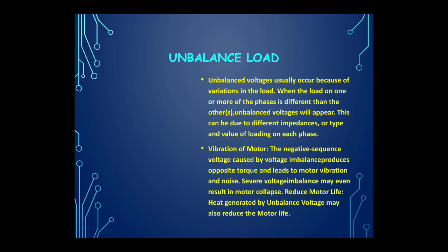Now the vibration of the motor. So what is the effect of the unbalanced load? In case of a three-phase motor, if the load is unbalanced, then the negative sequence voltage caused by the voltage imbalance produces opposite torque and leads to motor vibration and noise. Okay, the direction of the torque is changed.